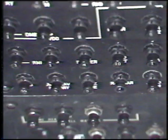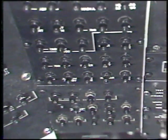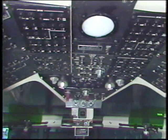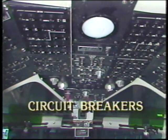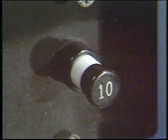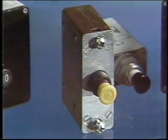While fuses must be replaced once they've done their job, circuit breakers may be reused. Circuit breakers are simply switches that open a circuit when too much current flows. Circuit breakers may be designed to sense current flow directly or may operate according to the amount of heat generated by current flow.